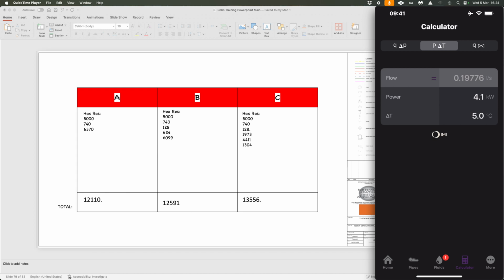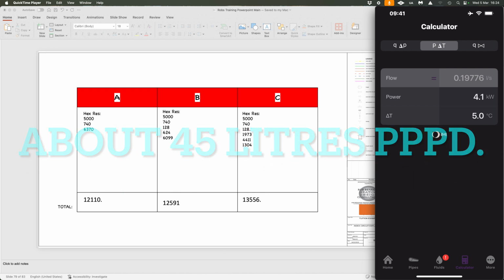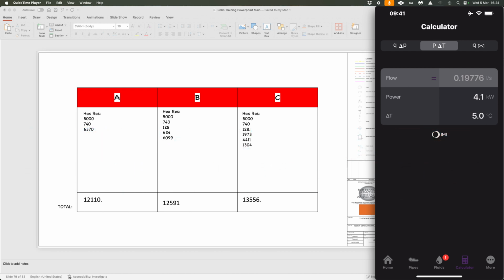Now, you might decide that if you've got a low temperature system and you've also got a hot water cylinder in there, you then need to look at what the pressure loss is through the heat exchanger of the hot water cylinder, and find out what the kilowatt rating is of the hot water cylinder, and you might need to size for that if that is more important to you for sizing for hot water. As we've discussed on many forums now, with oversizing of heat pumps, a lot of them we do size for hot water more than anything else, and it doesn't matter too much if we oversize, around 20%, as long as you can get lots and lots of system water volume in.